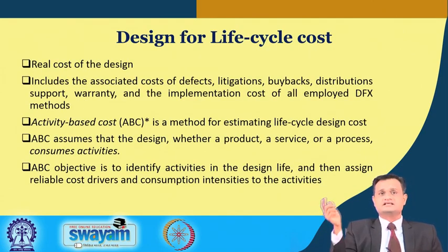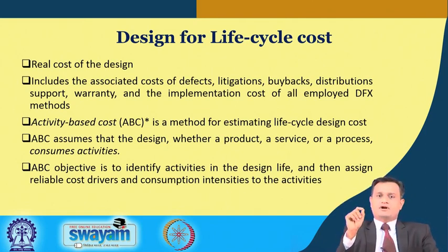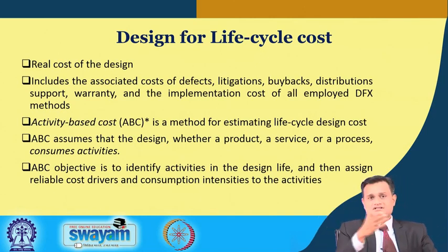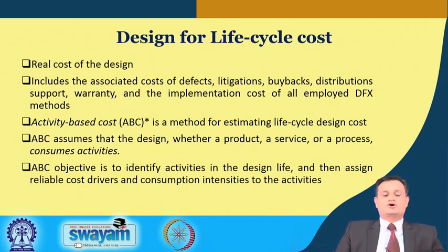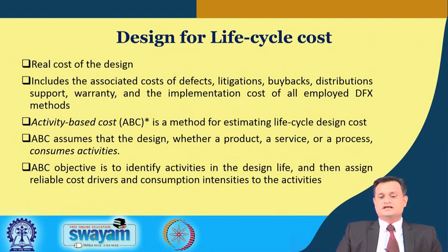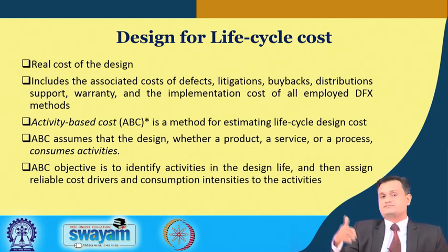Another X is design for life cycle cost. So please remember that my product is not used only for a small period of time. I must see what the total life cycle cost is. So this is the real cost of the design. This will definitely include the cost of defects, litigations, buybacks, distribution support, warranty, implementation cost of the employed DFX methods, and all this will add to the life cycle cost.